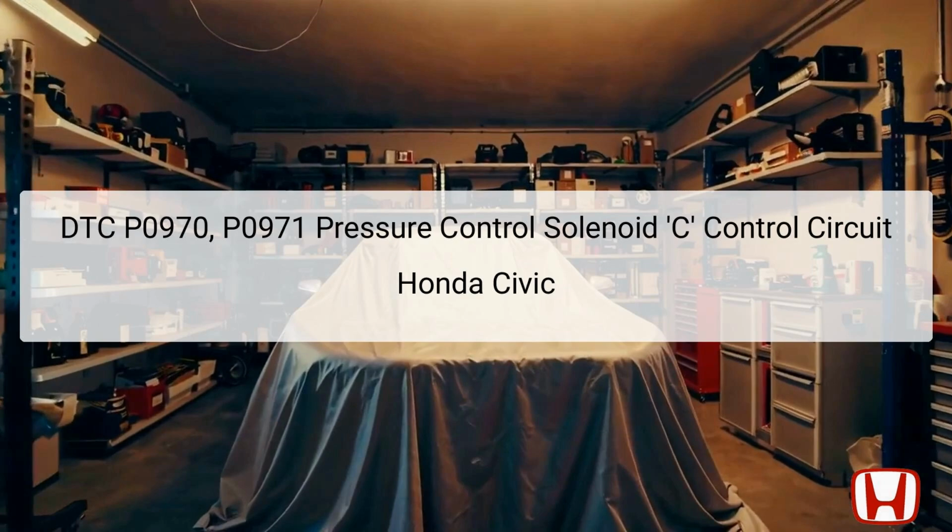The diagnostic trouble codes DTC P0970 and P0971 indicate issues within the pressure control solenoid C circuit in the Honda Civic models from 2016 to 2021. DTC P0970 is related to a low control circuit problem, while P0971 signifies a high control circuit issue.